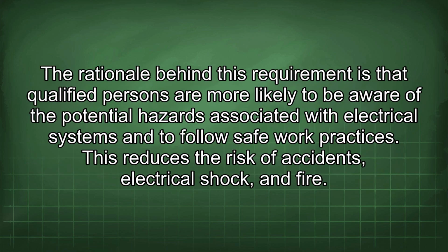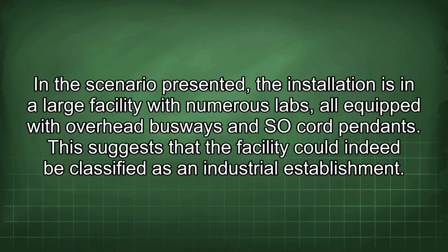The rationale behind this requirement is that qualified persons are more likely to be aware of the potential hazards associated with the electrical systems and to follow safe work practices. This reduces the risk of accident, electrical shock, and fire. In the scenario presented, the installation is in a large facility with numerous labs, all equipped with overhead busways and SO cord pendants. This suggests that the facility could indeed be classified as an industrial establishment.